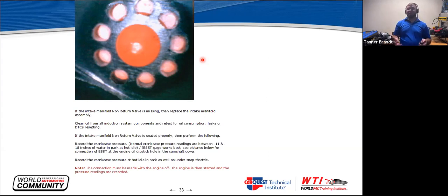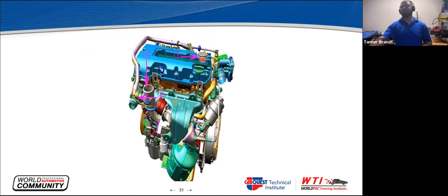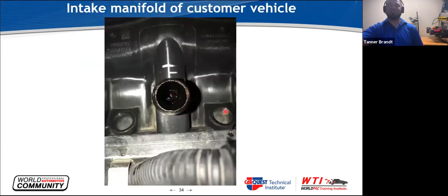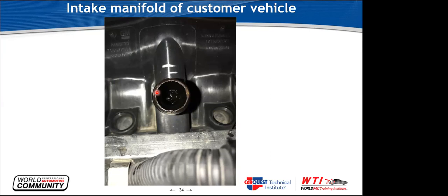And when that gets soft and you have vacuum coming across this, what do you think happens if this gets plugged? Where does the vacuum end up? It ends up right here. So I'm going to show you how we end up from here to here. So anybody, what do you think is going to happen, or what do you think it could do? Turn your turbo into a salad shooter on a bad day.